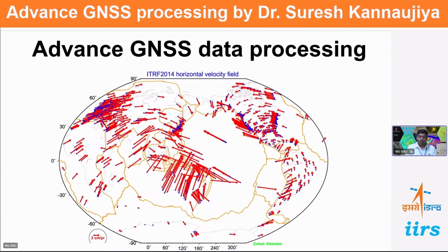When it is hitting the antenna and acquiring all those signals from different PRNs, for instance, GPS like PRN1, PRN2, PRN3, PRN32, it will always be in sub-millimeter accuracy.